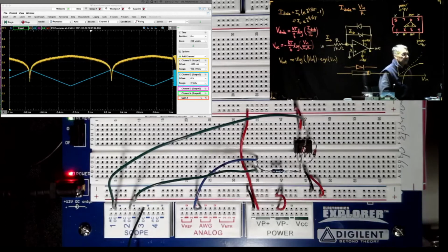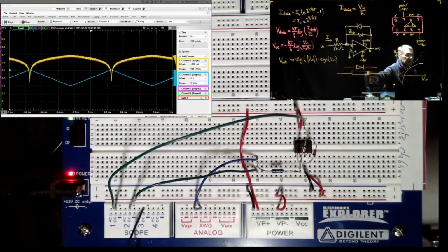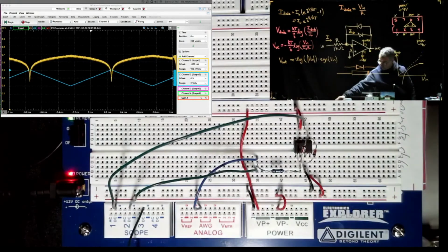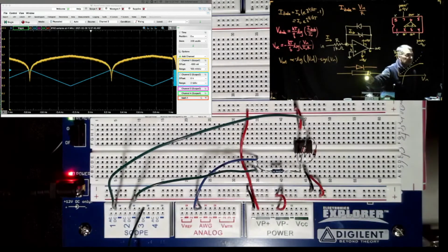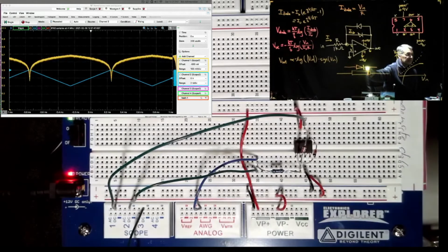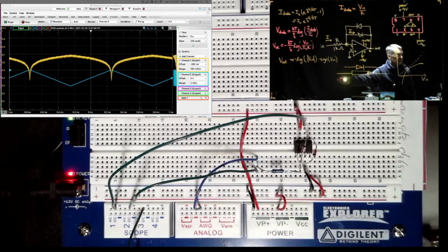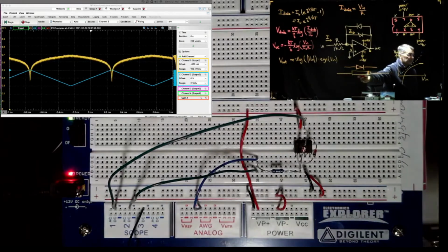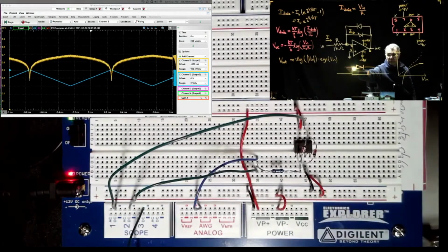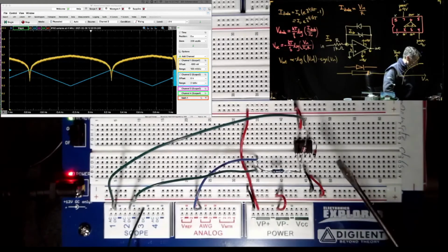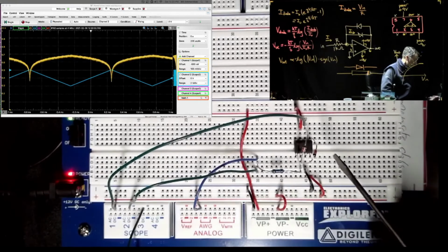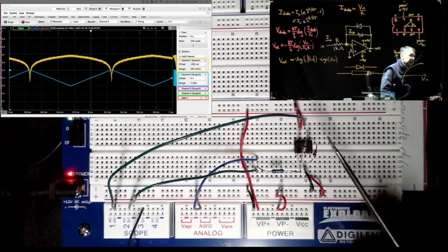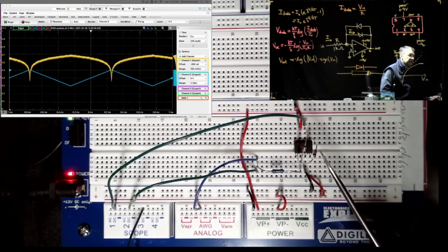So the stripe on the diode package corresponds to this line after the triangle in the symbol. The direction of allowed current flow is toward the stripe, in the direction of the little arrow on the diode itself. So we had to connect one of them with the stripe pointing toward pin 2 and one of them with the stripe pointing back toward pin 6. You have to make sure you put the two in opposite directions.